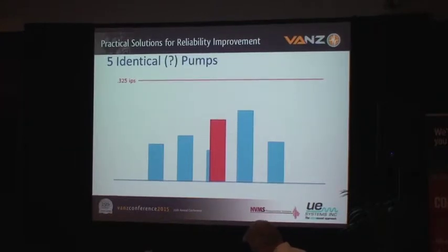How many of you have had that kind of experience? I mean, to me, it's fundamental. We're looking for changes. We're looking for changes that indicate something bad's going on, and we've got to react to it. And if we don't react to it, like I said, it's going to get real quiet, and everybody's going to be happy because it's not going to be making noise anymore. Of course, it's also not going to be pumping water and supporting the cooling load inside the plant. But that seems to be a secondary issue when it wasn't vibrating at 0.325 yet.